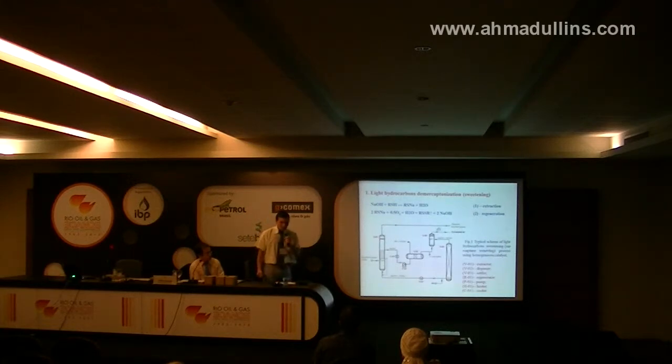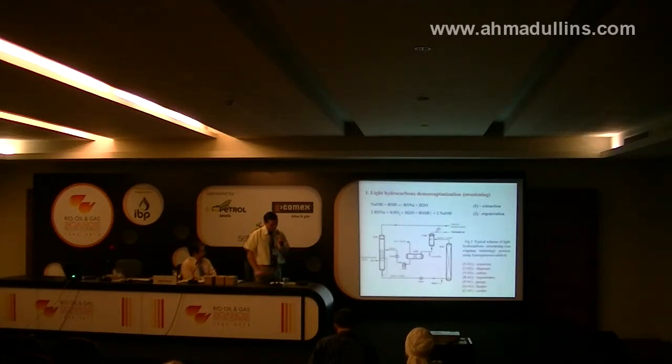The same problem was observed in the Ryazan refinery of Russian operation, while sweetening butane-butylene fraction performed in the presence of IFCAS alkaline catalyst solution. In butane-butylene fraction cleaned from mercaptan sulfur up to 2 ppm weight, there was up to 20 ppm weight sulfur as disulfide. It was found that in the regenerated alkaline catalyst solution, immediately after cleaning disulfides, the content of mercaptan was higher by 30–50% than at the entrance of alkaline solution in the extractor.